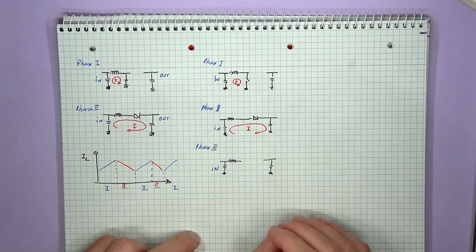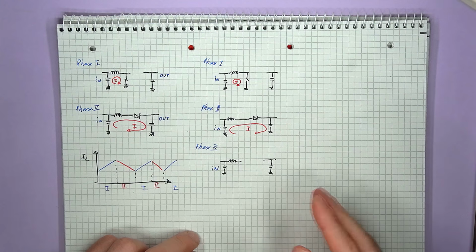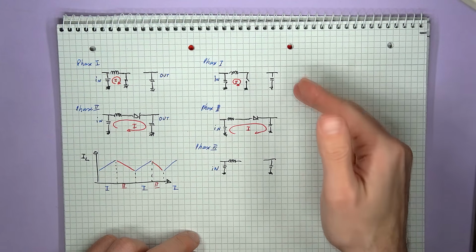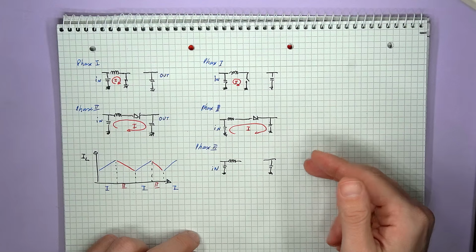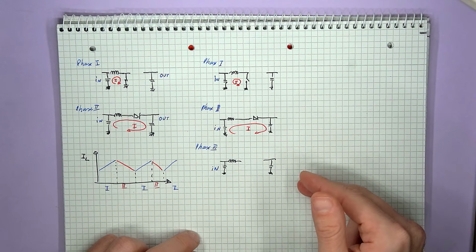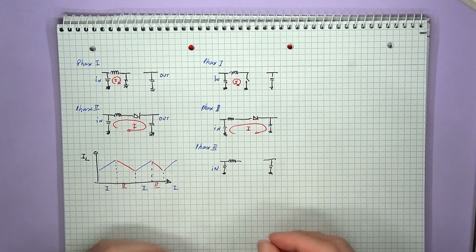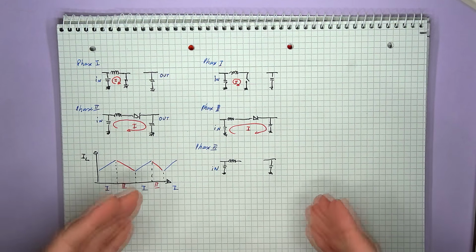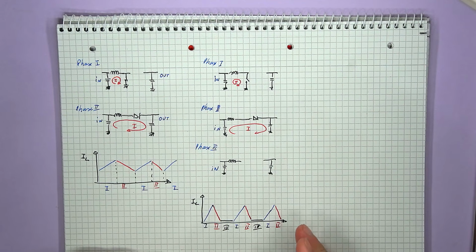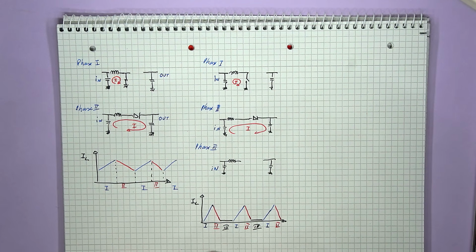Now, depending on the component choice and load, we can, however, get a third phase appearing. So, other than the inductor charging and discharging, in certain cases, you can end up with a state in which the inductor runs out of energy, so no more current passes. At this point, none of the switches in the converter are conducting any current. And this leads us to discontinuous conduction mode. This is characterized by a period in which the inductor current is stagnant at zero.